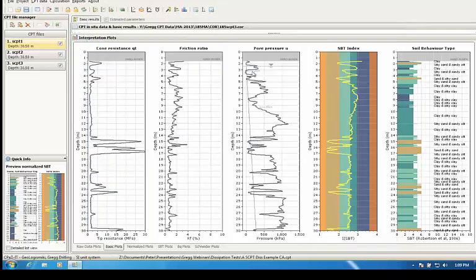But more importantly, the pore pressures were negative pushing through the upper silty sand, and they were positive in the underlying clay. And so you're seeing this sort of macro layering effect, where the negative pore pressures are where it's still being somewhat influenced by the sand, but beginning to be influenced by the clay below, where you got these positives. So it illustrates that you get these very complex dissipation curves.